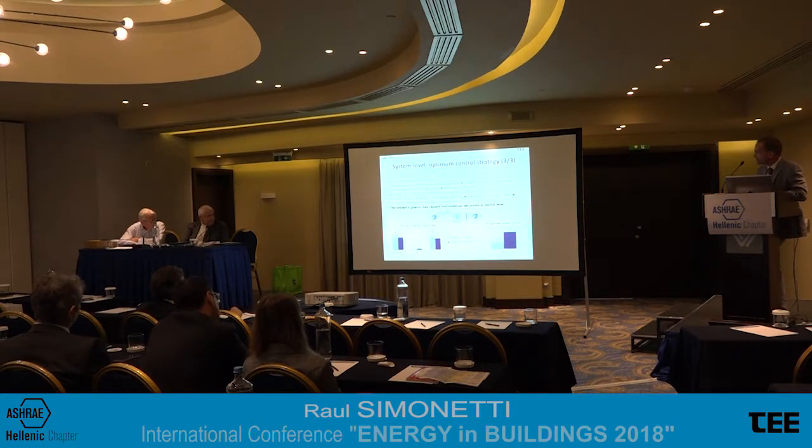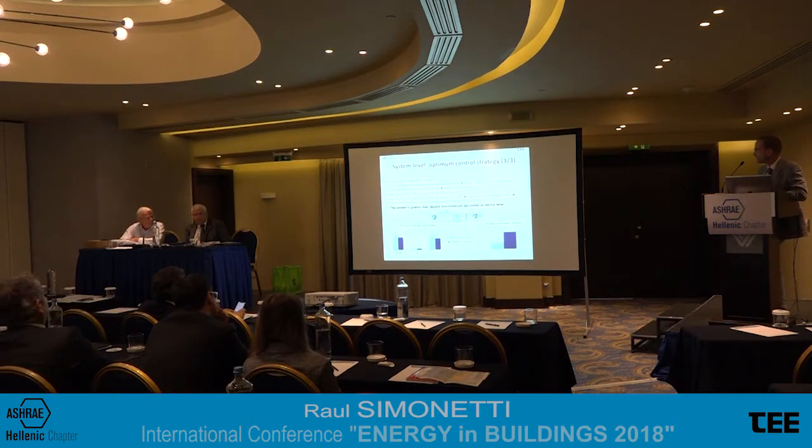So the light blue bars represent the total primary energy input when both the evaporative cooler and the cooling coil are running at their minimum duties, in order to guarantee the minimum humidity required and the minimum temperature required.